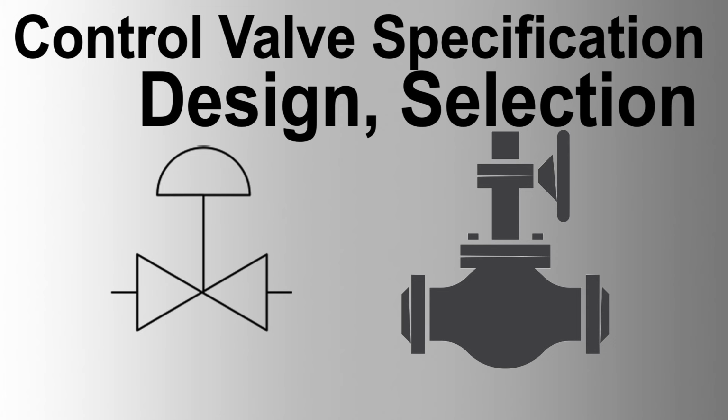3. Flow control. Example, crude oil pump discharge to export pipeline. Type of valve, flow control valve, FCV. Design considerations, body material, carbon steel or stainless steel depending on crude oil properties. Trim material, tungsten carbide for erosive surfaces. Valve type, globe valves for fine control, rotary valves, e.g., butterfly or ball valves for higher flow capacities.